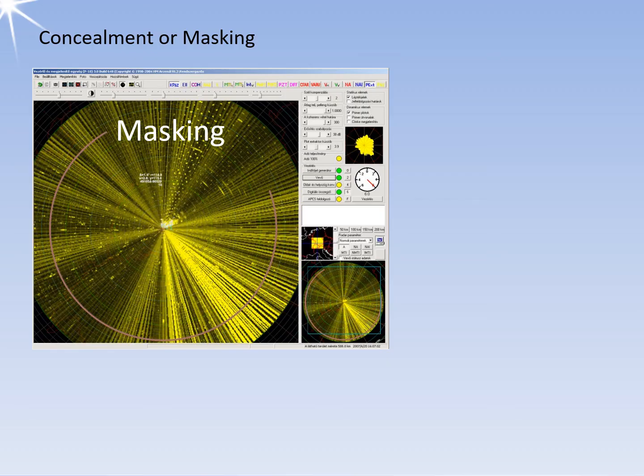Jamming can be divided into two methods, known as concealment or masking. Masking usually uses some form of noise as the transmitted jamming signal. Jamming can be achieved by transmitting high-power signals to an enemy receiver. By using noise modulation, it becomes difficult for the enemy to detect the jamming. This lowers the enemy's signal-to-noise ratio, SNR, to a level where they cannot receive the desired signal with sufficient quality.